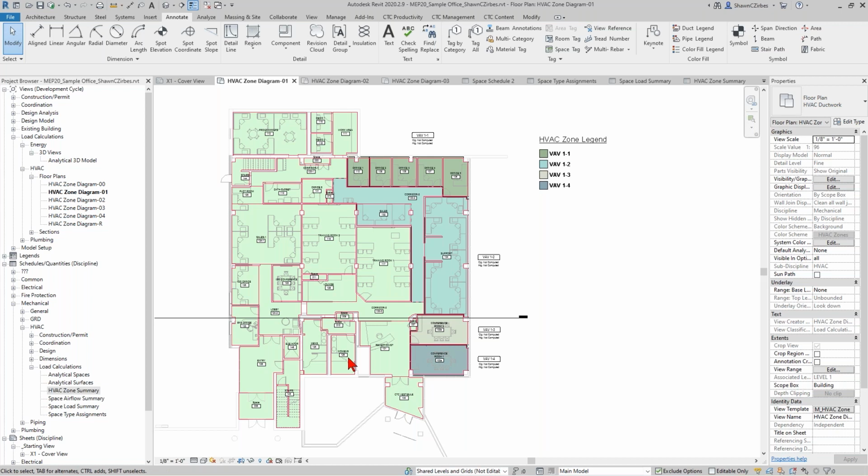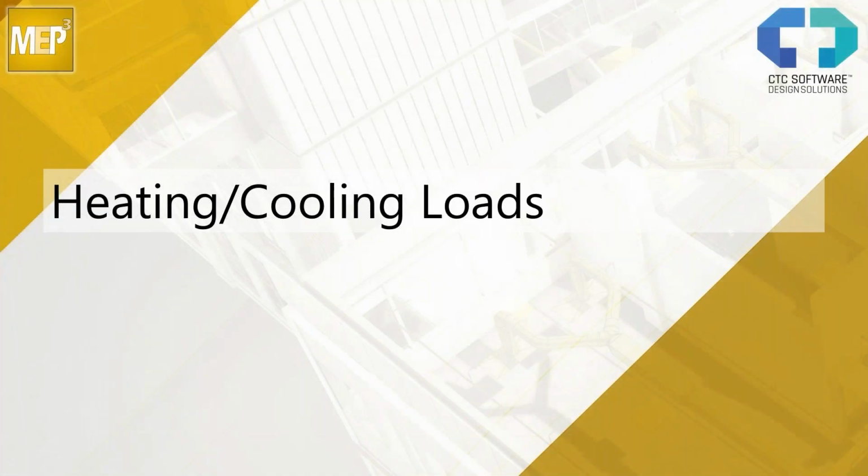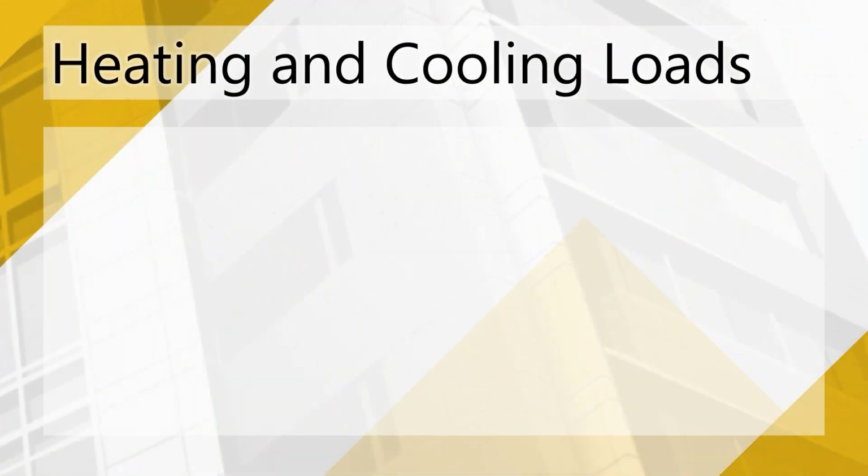Now, for sake of time, I'm not going to fully zone out all of this portion of my building. I'm going to jump over into doing some quick preliminary heating and cooling loads over here. We're going to talk about two ways of doing this. So method number one, great early quick analysis methodology, is directly internal to Revit, just native Revit, nothing special needed. As long as your room properties are set up, you'll get ballparked to the right area out here.